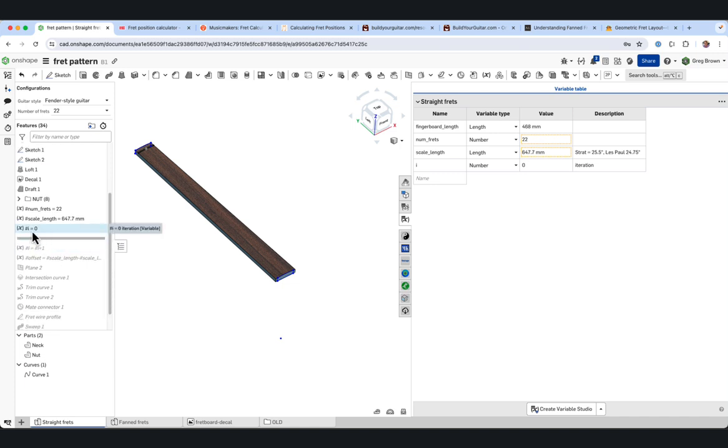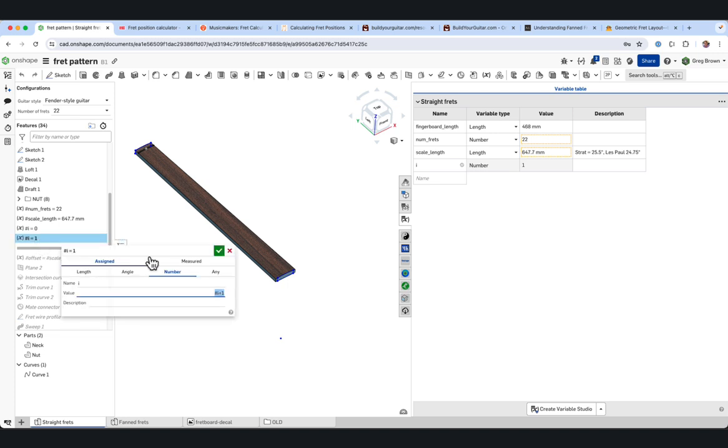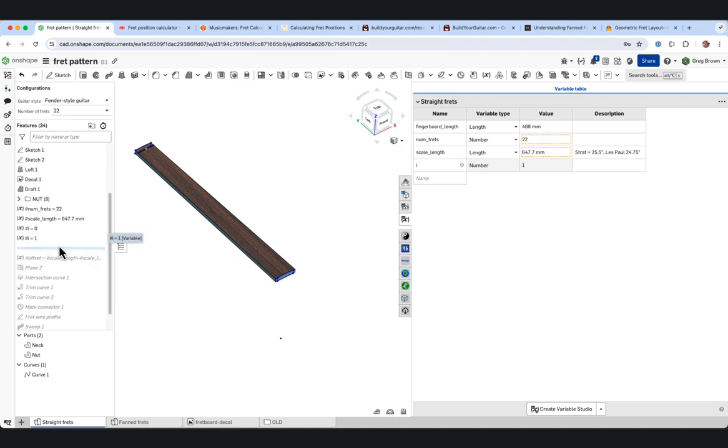So the trick is that you define the variable I and initialize it at I equals 0. Now, the next one is non-intuitive, but I tell you it's going to be a great thing when you work this out and get to use it yourself. You redefine I, but you say I equals, and then you use the same I, hash I, plus 1. So this is the first loop. So this is I equals I plus 1. That is the blindingly cool moment that you've been waiting for, because now we can continue doing some features.